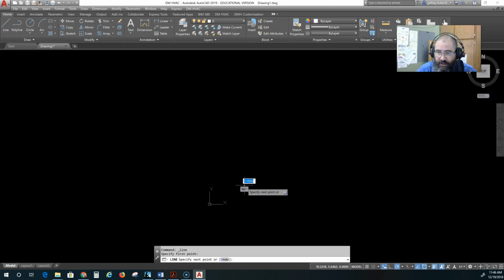Now once I place a line, or a start point, and I start to draw the line, it is now referencing that first point. So this becomes a relative coordinate versus a Cartesian coordinate or a system coordinate. So everything I do here is based off of that last point. Now I can enter other points by the user coordinate system or the Cartesian coordinate, and I have to just click on a different tool, and I forget, to be honest with you, what it is. Oh yeah, I think I have to turn off dynamic input.